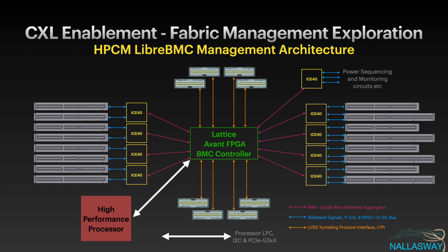And also they're using the LVDS Tunneling Protocol Interface, LTPI, which has been open sourced to OCP and adopted in the Data Center Secure Control Module, DC-SCM, as well. So we've got the basic hooks in here, and more work needs to be done. But this could be a wonderful exploratory platform as we research the fabric management pieces of a CXL enabled computing architecture.